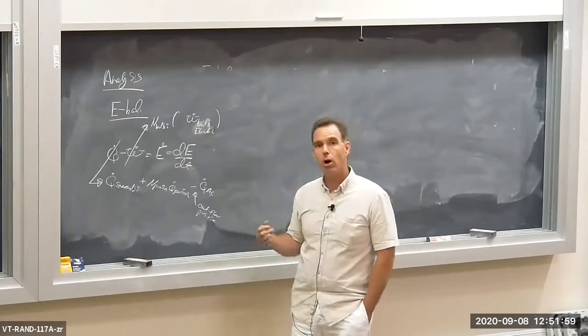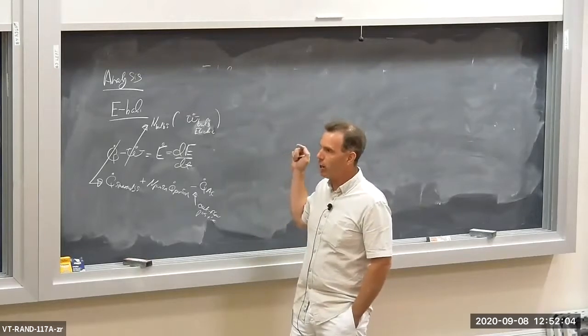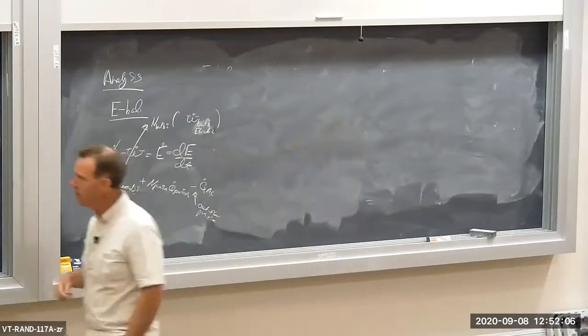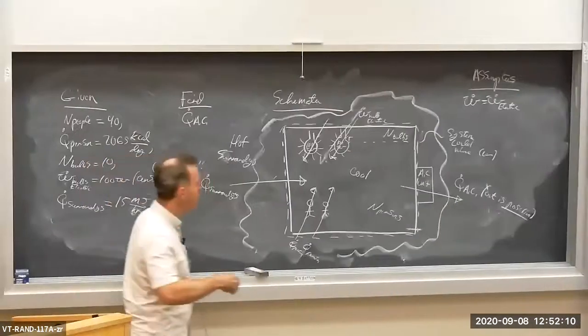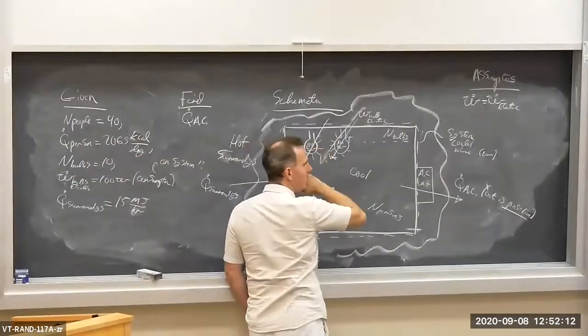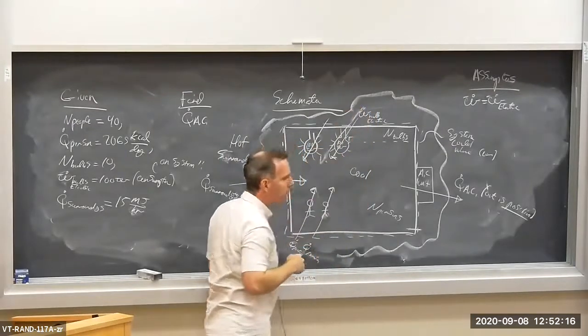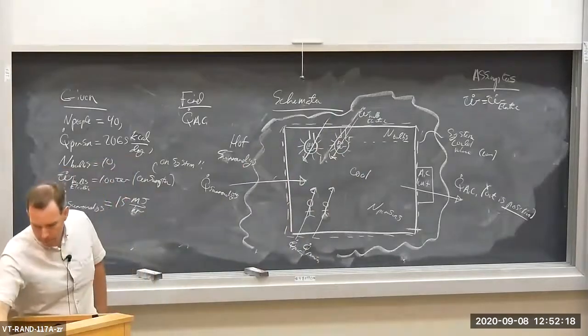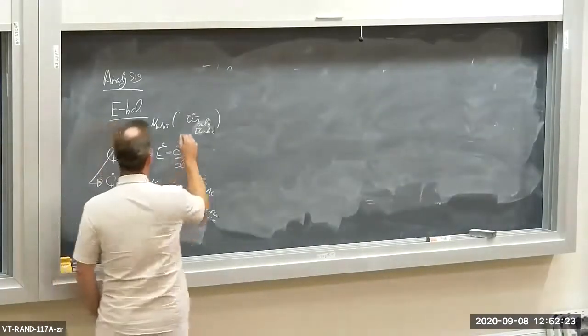The bulbs are consuming power, so electricity is flowing across the system boundary to power the electric bulb. So W dot electric is on the system, not by the system. So I got to put a negative sign right here.